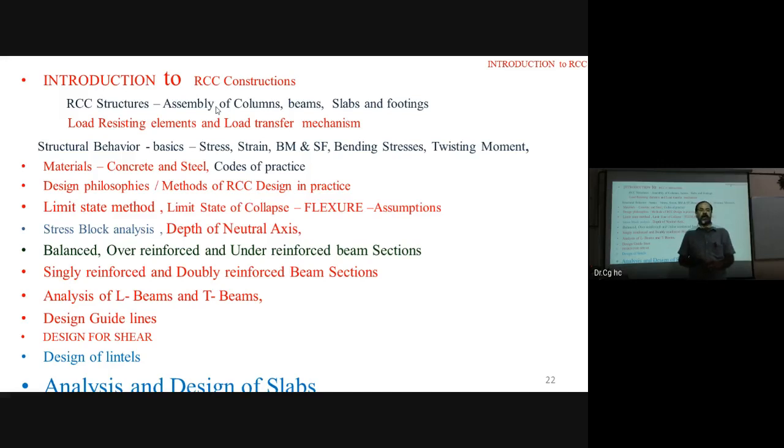This is one design of RCC slab, and related to that, the procedure: how to design, and where we have to start. In RCC design, they will give the span. A slab is a plate, a horizontal plate supported over walls, beams, or columns, isn't it? This is the plate, a 2D planar structure, with one X direction and one Y direction, X, Y.